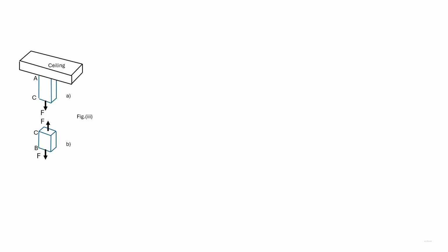We earlier considered a bar subjected to a tensile force. We then took a cross-section perpendicular to the axis of the bar at a distance from where the force was acting. We discussed that the stresses acting on the cross-section would be uniform. We mentioned that the resultant of the stresses would align with the axis of the bar, which passes through the centroid of the section.